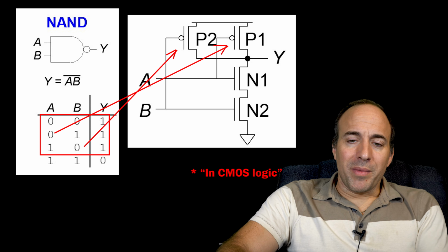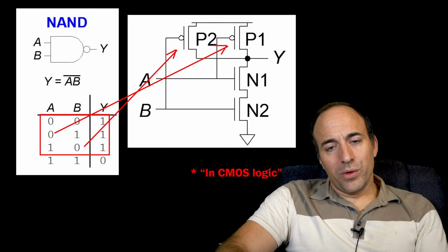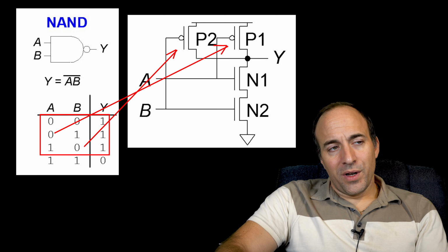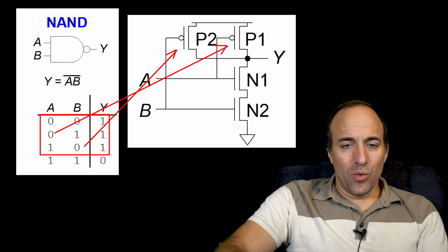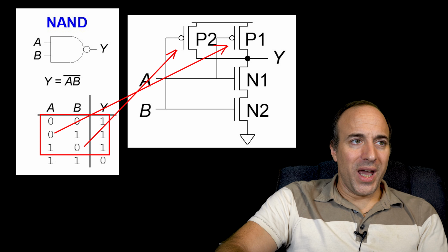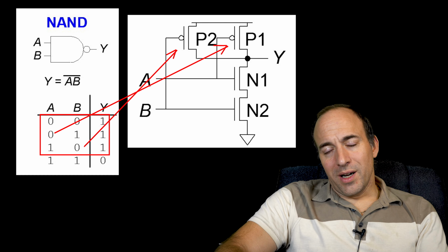The other thing to keep in mind here too is that in CMOS transistors, each input needs to be only connected to one PFET and 1 NFET. So if we had left in the 2 PFETs connected in series, we would have ended up with an imbalanced gate.